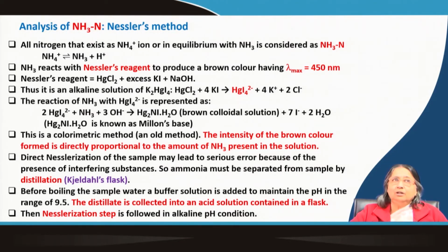In the sample water also you have added the Nessler's reagent, so it has already become some brown color. Now you are adding, in the blank where you have taken distilled water, the ammonium chloride slowly drop by drop from outside, from a burette, say. After some drops are added you will see that the color is matching. Then you will know how much ammonium chloride you have added, and then you know how much ammonia nitrogen is present there.